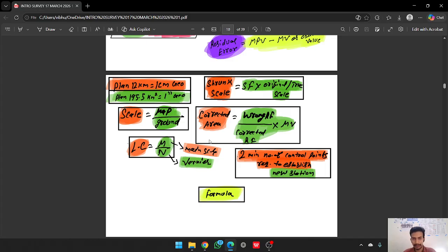After that, we discussed the types of principle. What is principle? There are two main principles of survey. First, working from whole to part, is known as the first principle. In this, we have to locate the main control points or measure points or stations, like A, B, C, G, the main stations. First, we locate the boundary.